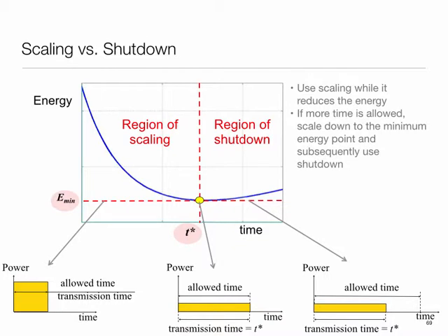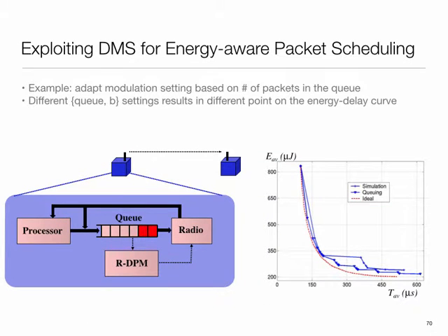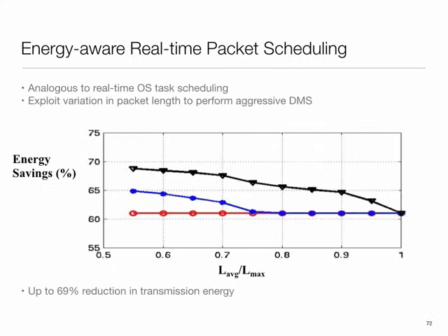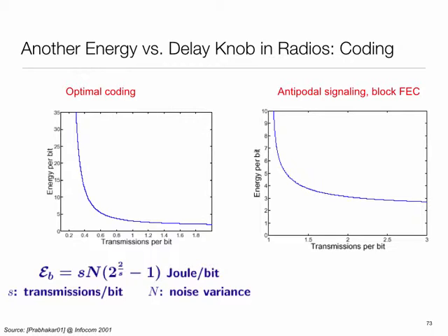So at this stage, in all the standards that exist, Wi-Fi, Bluetooth, and all, there are various kind of power management stuff built in for these capabilities. So this is an example of how, for example, the equivalent of dynamic voltage frequency scaling gets done for radios or network interfaces. The idea is a radio, there is a queue. Somehow I can change its modulation scheme, and again, Wi-Fi radios and all provide this capability. What the processor does is it monitors this queue. If the queue starts getting filled, you increase the rate. If the queue is relatively empty, you can reduce the rate. And because of modulation scaling, you have sort of significant benefits to be had. So lots of work along this direction of energy-aware packet scheduling, things like that. But these are at this stage kind of common part of the standards around us.